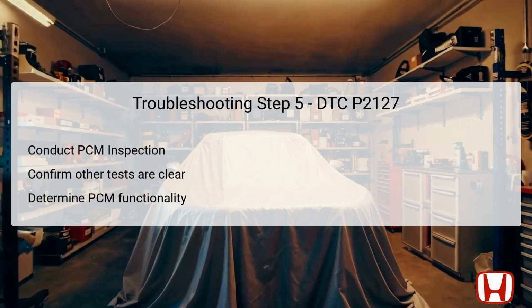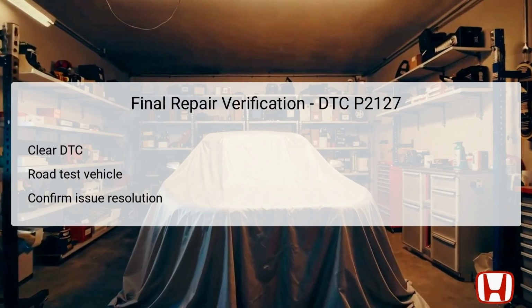If the PCM does not register changes corresponding to the accelerator pedal's position, it may indicate that the PCM is malfunctioning and may need replacement or reprogramming. Once repairs have been completed based on the previous troubleshooting steps, the final verification process is essential.